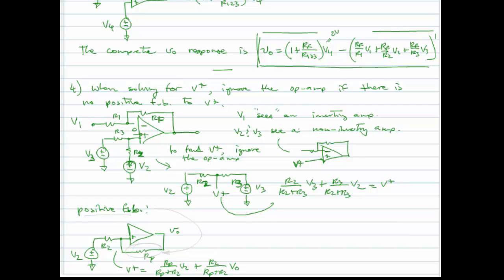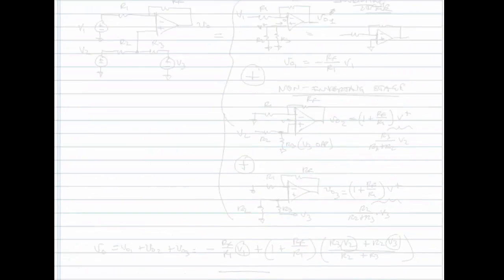All right. Now we're not solving this kind of problem right now, but I just wanted to identify how you would spot positive feedback. Positive feedback is indicated by a resistor, or some element, going from the output voltage back to the positive input of the op amp. The next one, which one are we on? What number are we on?